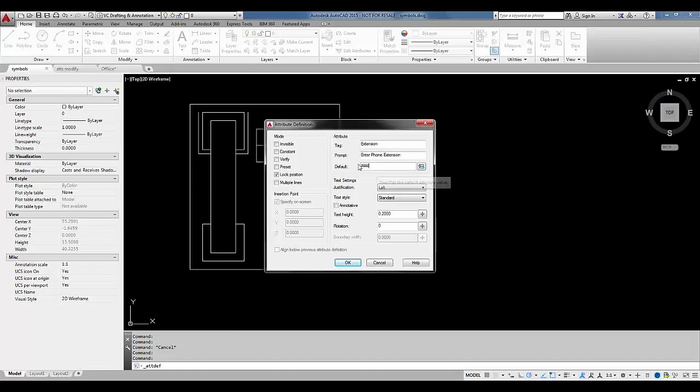Yes, that's a really key point, because a lot of times what will happen is you'll enter your attributes, and you'll show how to add those in a little bit. But if you have a default value, even if you leave that blank when you're inserting the attribute, it's going to show up with whatever you have for the default value. So we get a lot of questions from folks asking, why do I have a value there when I didn't enter anything? And it's usually because there's a default setup that somebody else might have added and the user wasn't aware of.